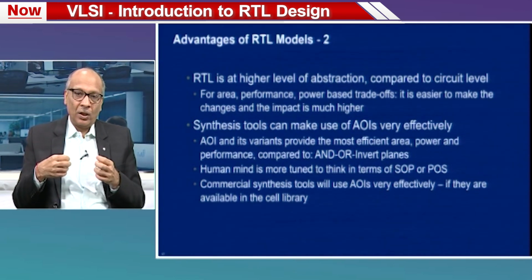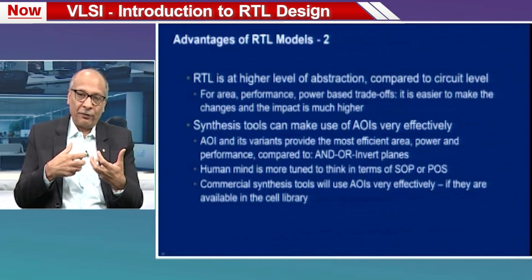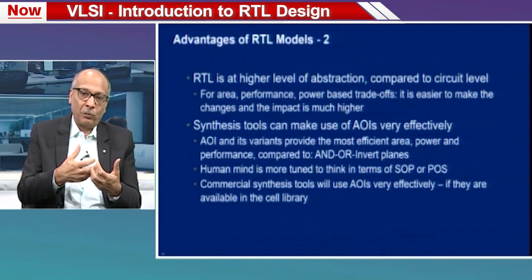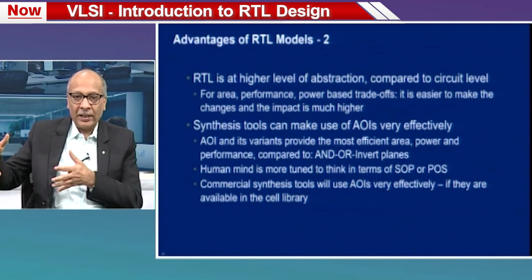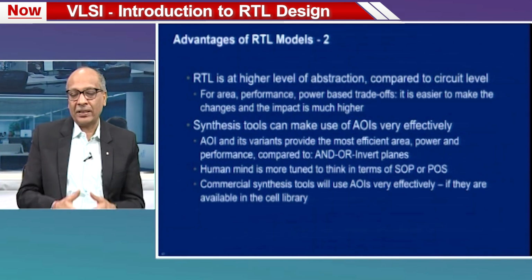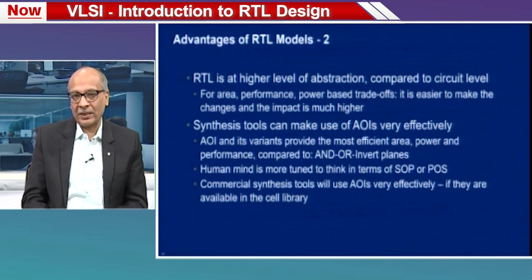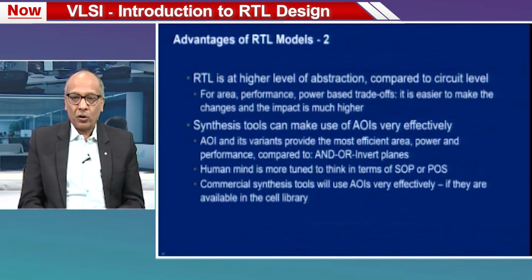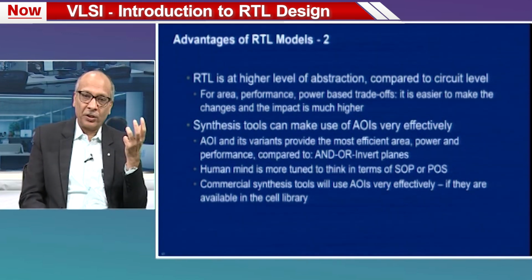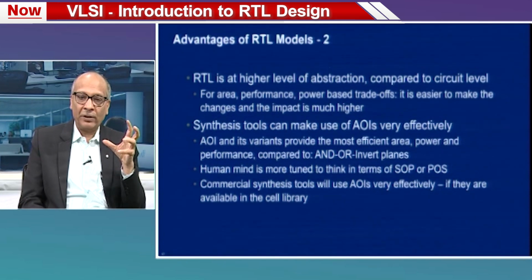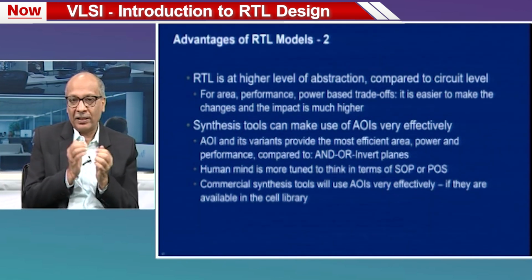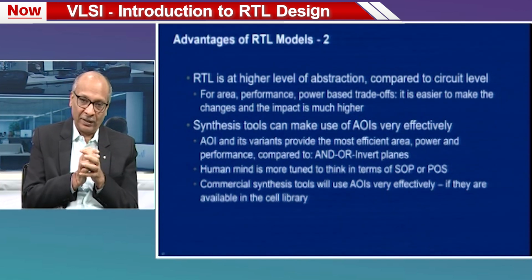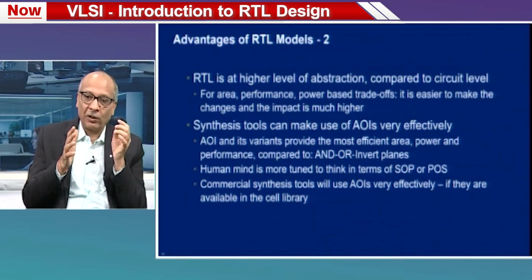Okay. So, if we have to realize the same functionality ourselves, we will put in an AND gate followed by an OR gate followed by invert, and that will take many more transistors. So, much more area, so much less efficiency in area and much more power. So, commercial synthesis tools will make use of AOI very effectively in order to realize a much smaller circuit with lesser delay and better power profile, versus the human mind, which will not be able to do that.